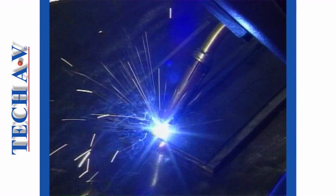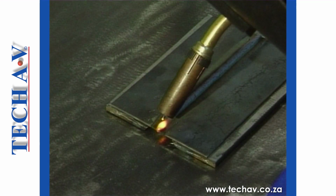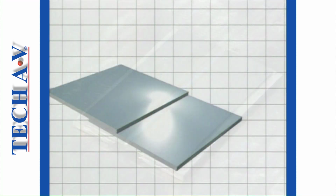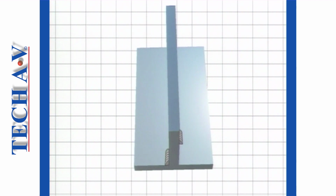Most welds, whether groove or fillet, are usually made as a continuous weld along the entire length of the members being joined. However, a weld specification may call for an intermittent weld to be deposited in segments. Depending on the joint configuration, these segmented welds could be staggered on either side of the joint.